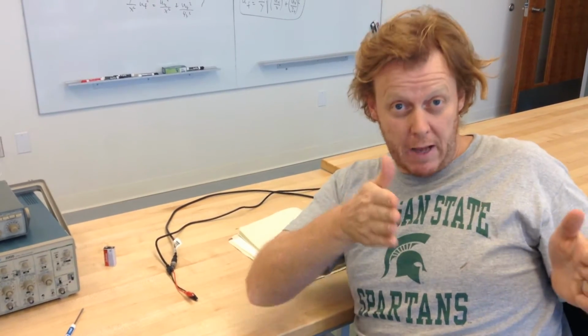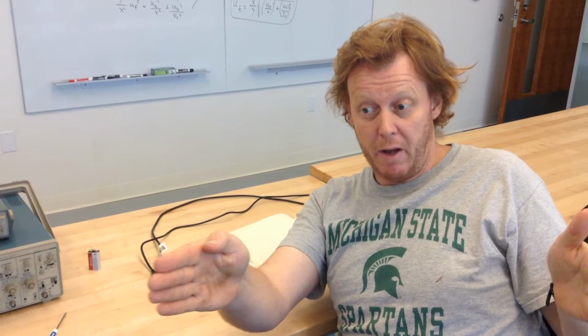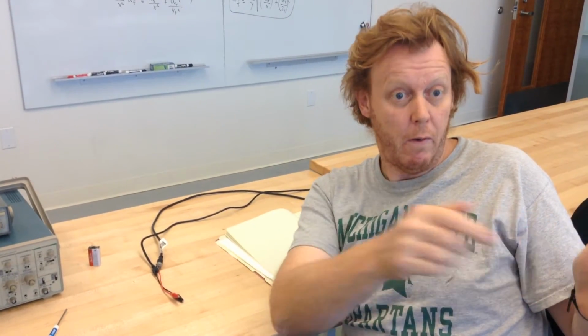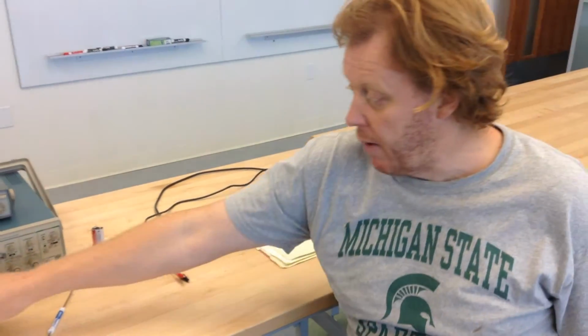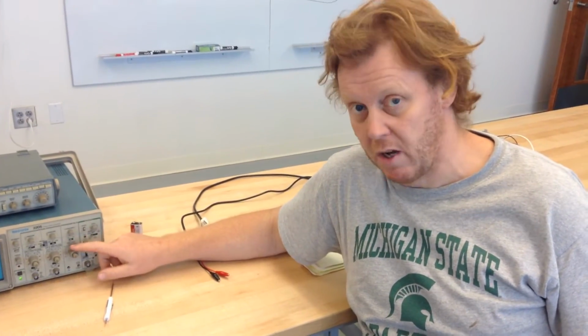And they pass between two capacitor plates, and the voltage goes slowly positive, pulling them to the left. It goes slowly positive, then back to zero. Positive, back to zero. So it's a ramp voltage. If you were to look at voltage as a function of time, it would slowly increase, then drop down to zero, slowly increase, and it'll do that per sweep. And we can control that voltage signal inside the oscilloscope with this knob here.